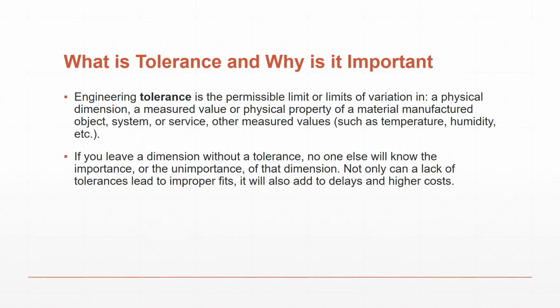The reason why tolerancing is so important, the easiest way of doing it is just to always remember that in a perfect world, everything would be created perfectly. But in a fab shop, depending on what you're creating, there's different kinds of bend radiuses and the saw blade thickness and things of that nature that do interfere with those perfect measurements. So a tolerance gives people a chance to have a little variance in it, not to really have a hard sell on it, so they don't make a mistake.